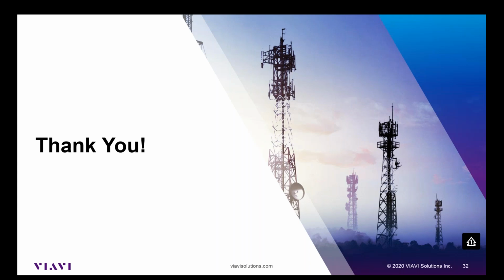Bill, I'd like to throw one more thing in there. I've talked to a few customers that have gotten bit by this as well. They'll have a huge power supply, 50 amp power supply, and they'll have their cable loss compensated for, but they'll be testing their 50 watt radio with like 20 gauge wire. So make sure that not only you have a sufficient power supply, but that the wire is big enough to feed that radio as well. Right, 10 to 12 gauge for sure.